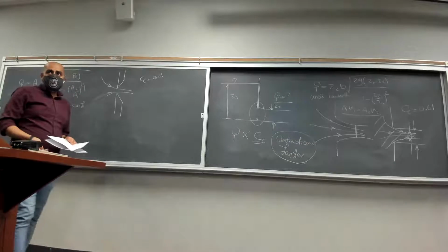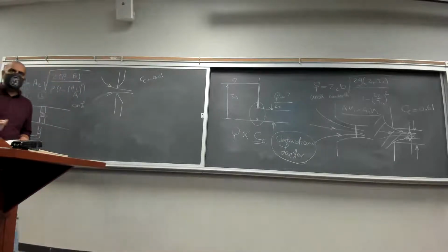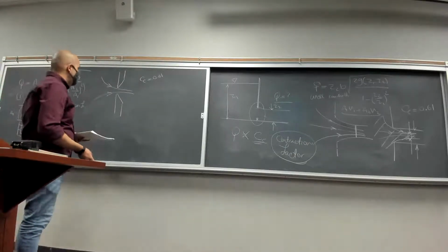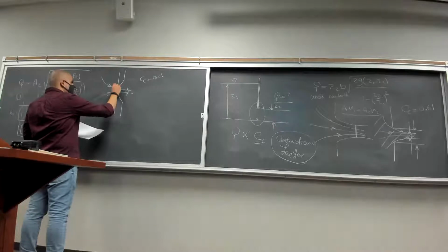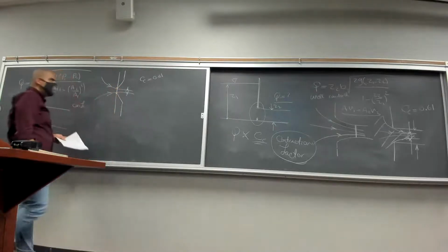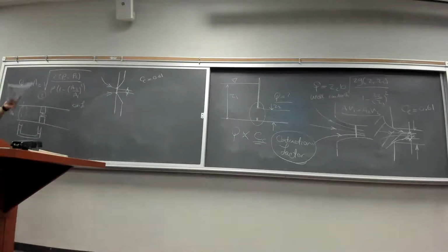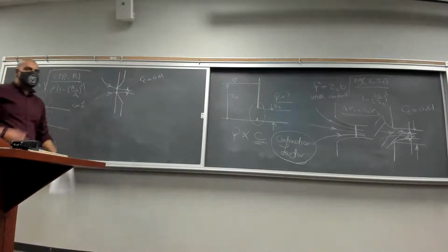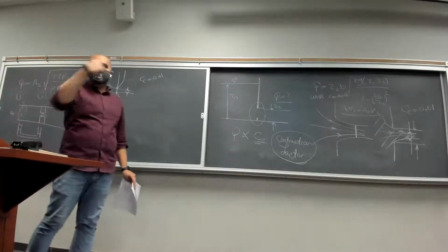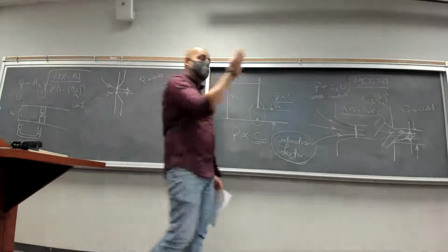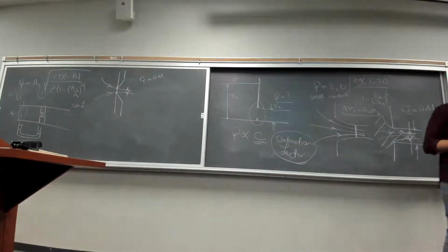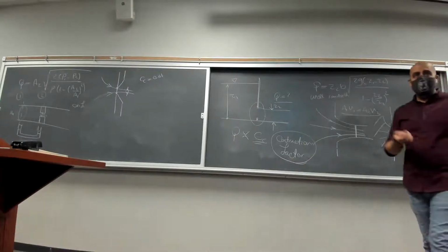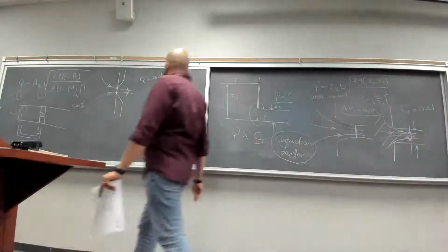You may want to ask, where did we get this contraction factor? This is essentially based on experimental analysis. And it's the value of this length compared to this length, right? So this value is telling you that 39% of the cross-sectional area of the pipe is not going to be covered by the fluid. This is at the beginning, okay? When that's at the entrance of the fluid.